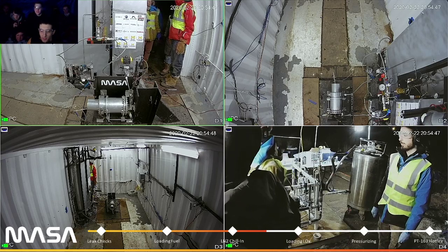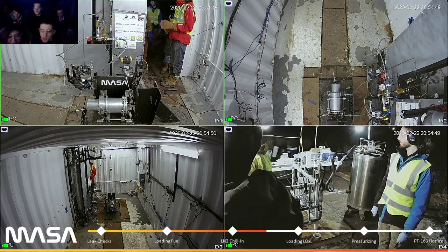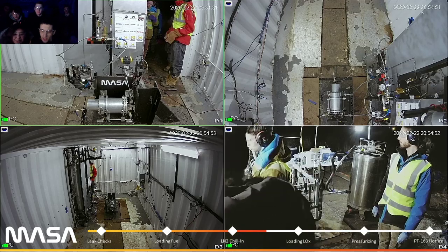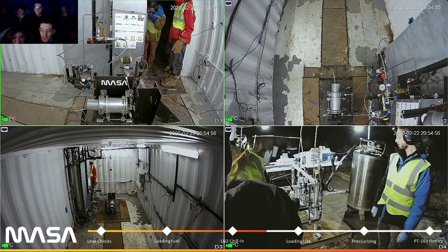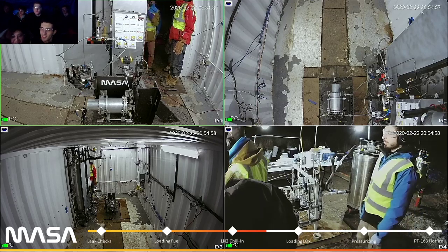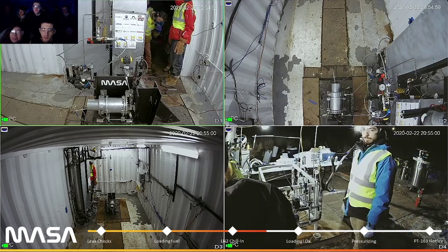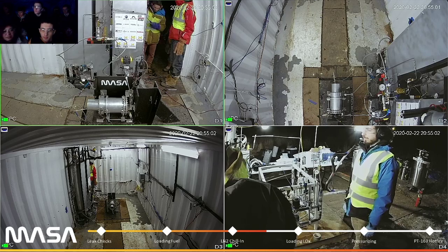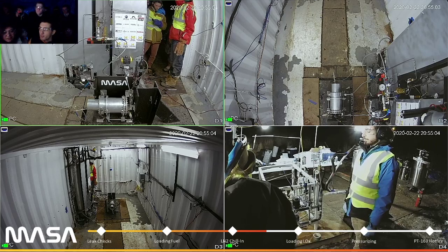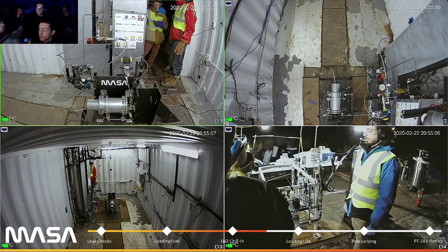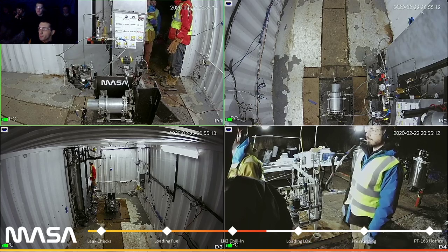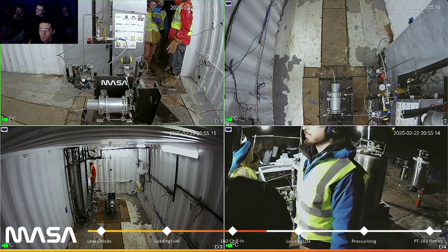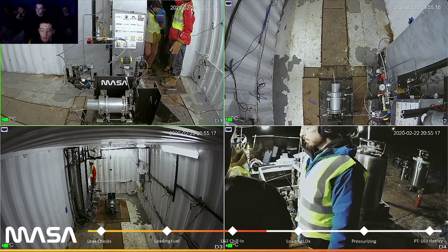The only solids I've played with are... Have you guys ever seen a liquid engine hot fire? We're just waiting for the liquid to drain out. So you say more M dot, but our engine's limiting factor is the injector and the propellant pressure. If you want to have more flow into the engine, you have to either make a new injector or you need to have higher pressure propellant.